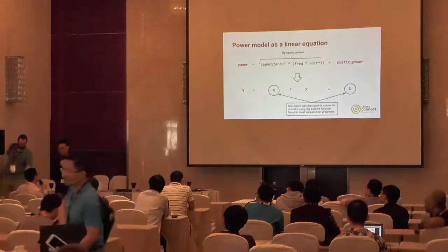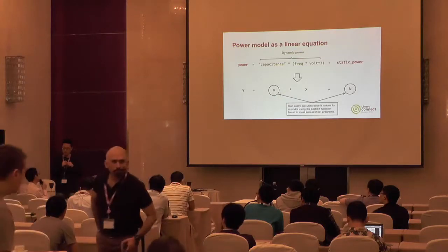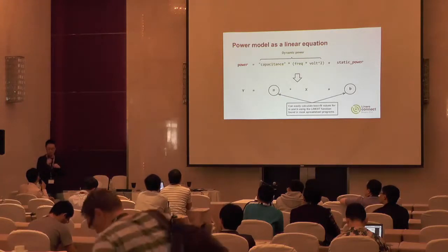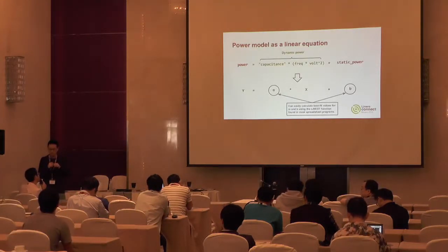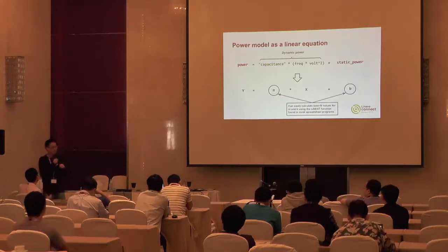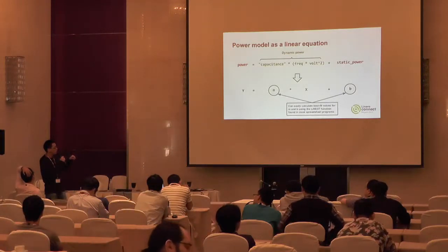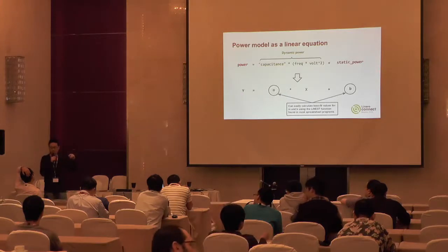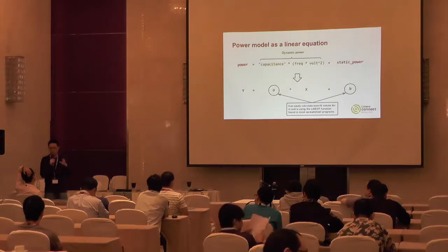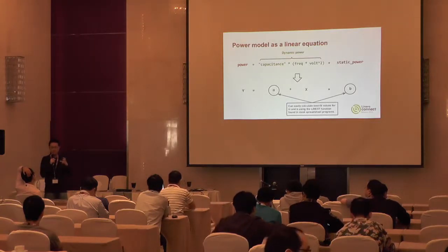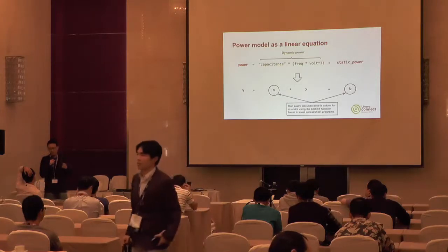Sometimes it's not only the leakage. When some of the CPUs are idle but the cluster part is not idle, in this status all the existing power belongs to the static power. This is why we cannot measure the cluster level static leakage. Why? Because at cluster level we don't have a specific state to disable the clock for the cluster.